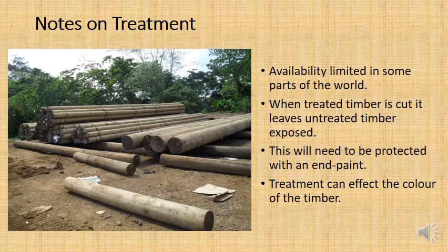But a lot of the timber that's being imported from Turkey is treated, or sometimes they say it is treated even though it hasn't been. So you've got to be careful there. And when you cut it, you need to paint the face that has been cut with an end paint, because that face will not have the chemical treatment, because the log or the lumber or the timber was put in whole into the chemical treatment tank.